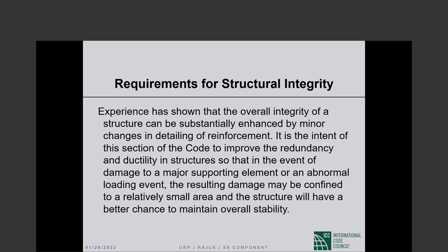A few of the questions are very general, like: in footings or pile cap, where should we place the temperature or shrinkage reinforcement? In the top of the footing or pile cap? I specifically covered this, the same answer as for mat foundation. It is up to you. If you think it will do the most good near the top surface, that's where you will place it. If you think the bottom surface will do you more good, that's where you will place it, or you can distribute it between the top and the bottom.